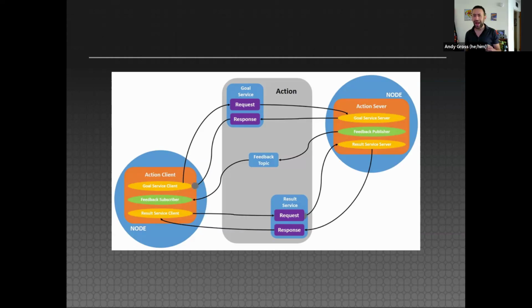This then brings us to actions. Whereas a topic is just constantly giving us information like temperature, a service is doing things like, you could say to a robot, hey, report the current load on a joint, right? That's not information that you probably want to have constantly being broadcast, but you might want to have a way of inquiring, and that's what it does: it asks and then gets a response. And then actions are a means of control that use services and topics to initiate a request.